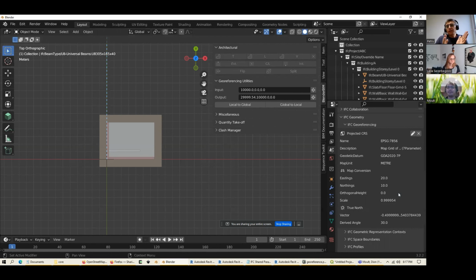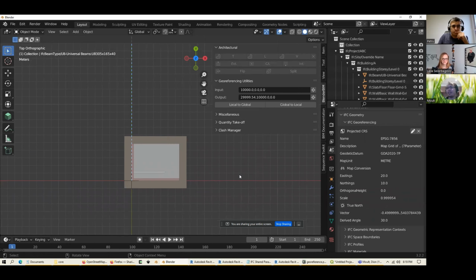All right. That makes sense, Dan. So I guess the summary is, at the very beginning of the project, get your architect, surveyor, and a third party who will sanity check both of you in one room together and ask them: projected CRS name, get the EPSG code, eastings, northings, the angle of rotation, get it in a few different variants, DMS, DD. If you're really geeky, you can do the conversion to abscissa and ordinate, the combined scale factor, and then ask for a site survey and a site drawing.